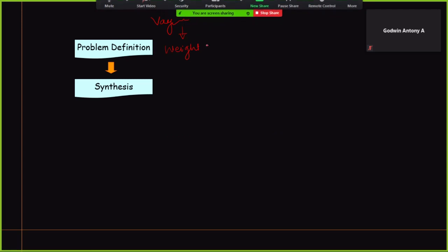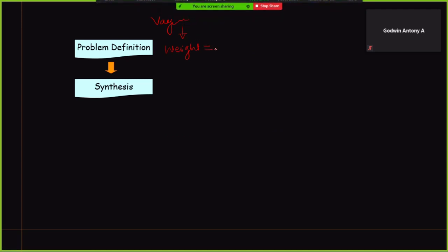Yeah, so first of all we'll define as a parameter the maximum weight it can carry. Maybe 60 kg plus, and the weight of the bicycle is maybe 20 kg plus more weight. We may go for 100 kg as the maximum load it should transfer from one place to another place. Then another parameter we will define is speed. These parameters are typically called the problem definition. This is the way we define any problem in terms of numbers. The maximum speed will reach 10 kilometers per hour or something.